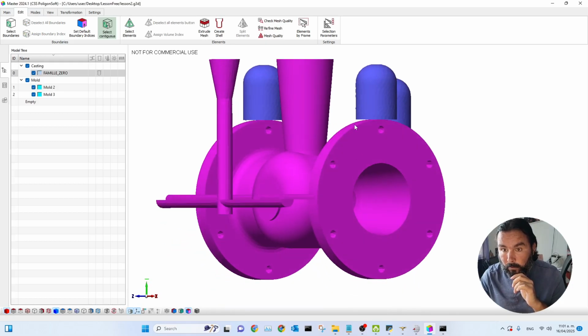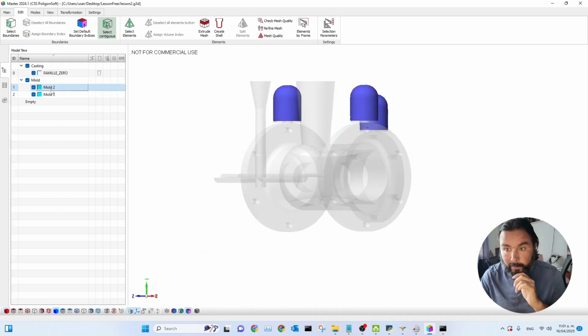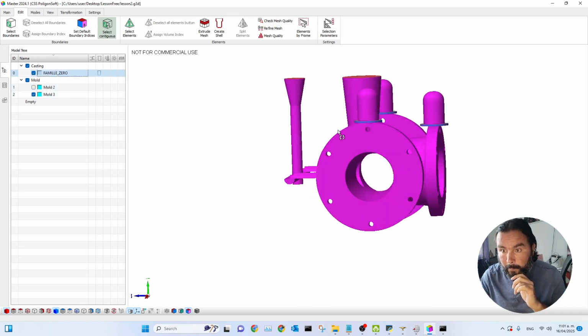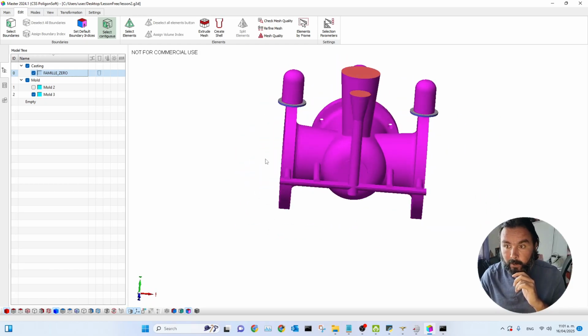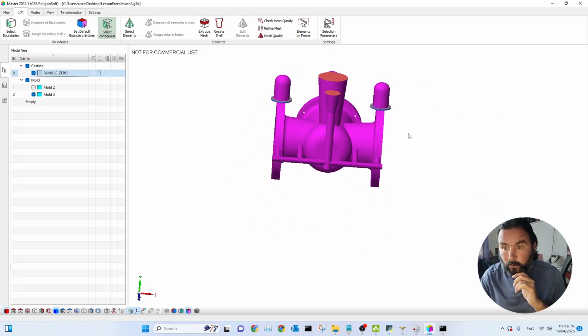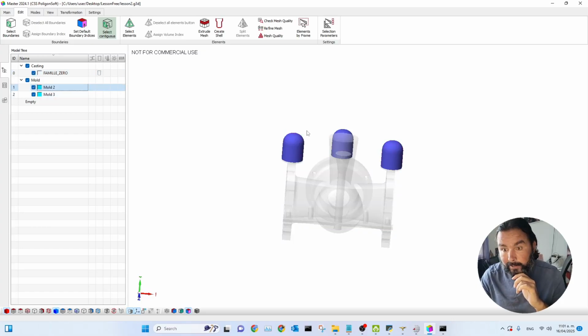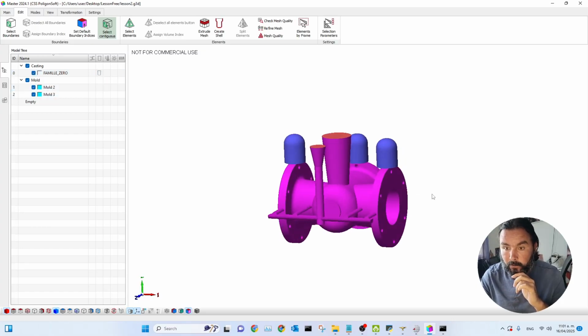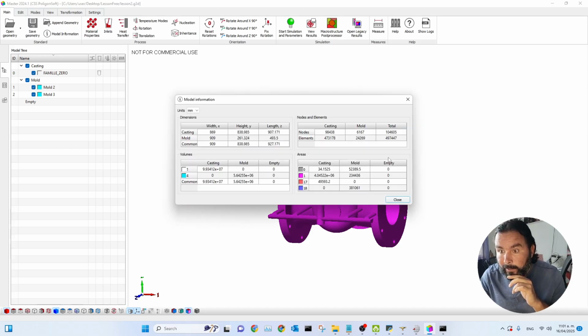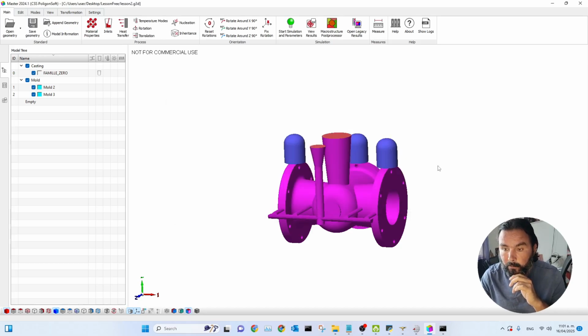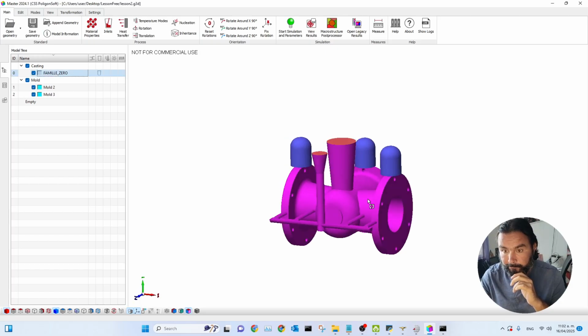We have managed to obtain 2 additional volumes, one being the sleeve itself, and the other being our ring. What are we going to do now to achieve a correct simulation? I repeat that this part should normally have been done during the creation process of the 3D model. We are doing it here simply to avoid leaving the program. I'll check the number of triangles again. Yes, I'm still within the limit, so I can run this simulation without any problem.